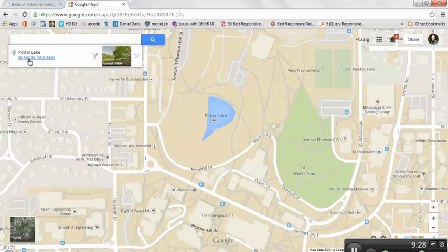So that 60 miles is an important thing to remember, because there's the big data set. It's going to have 21,000 data points approximately on one axis and 21,000 on the other. So if you accidentally tell it to make a surface with all of them, it will crash Rhino in about 3 seconds, because 21,000 is still way too big of a data set for Rhino. So we'll be trying to figure out what little tiny postage stamp of data we want, and that's why we'll leave it here to the 3 decimal places.